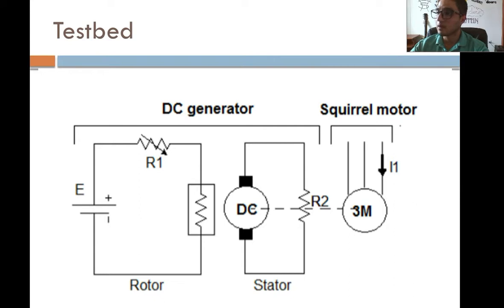The signals are measured in this testbed that includes a new motor mechanically coupled to a DC generator connected to a resistive load. Furthermore, an extra rotor, identical to the original but with two consecutive bars drilled, is used to emulate broken bars, and an extra bearing, whose outer race has been cut on one side, is also used to emulate seriously faulty bearings.